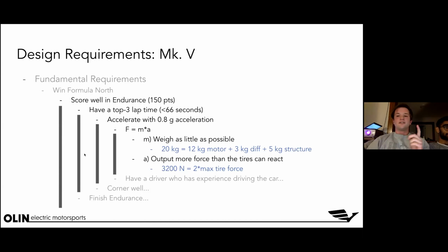Gotcha. Sorry. The factor of 2 came from the fact that we have 2 tires, and that's a per tire maximum force. But that's a good question. Another thing we can talk about later is factor of safety and margin of safety, which are design tools that you can use to account for uncertainty on your end, but also poor, not precise analysis. Did that answer your question?